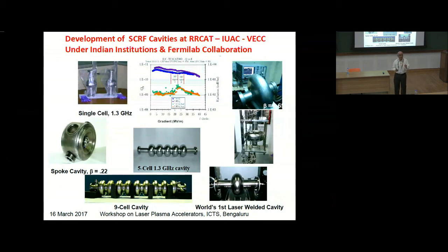It gets oxidized very fast. As soon as you put it in air, niobium gets an oxide coating. So especially when you heat it and when you join it by welding, it will get oxidized. And if the oxide layer stays somewhere on the surface, you have a superconductor-oxide-superconductor, an SIS junction, which is a lossy junction for the RF currents as they flow on the surface.